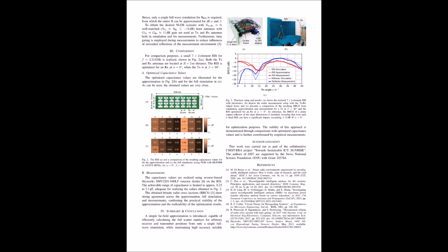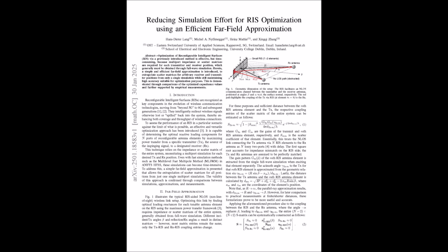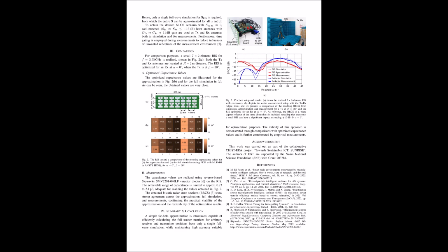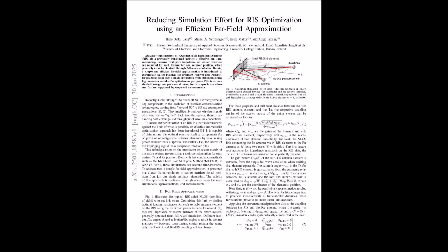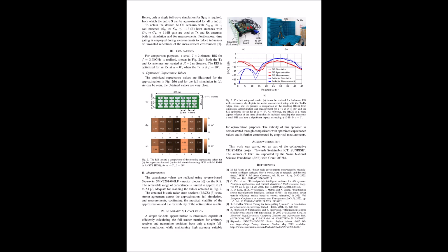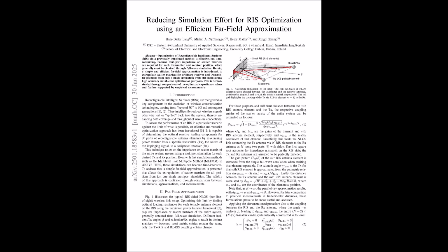And the values in this matrix, they can be complex numbers. Complex numbers, not just simple magnitude. Right, complex numbers, because we need to capture both the magnitude and the phase of the coupling. The magnitude of the complex number represents the strength of the coupling, and the angle of the complex number represents the phase shift introduced by the interaction between those two elements. Ah, the phase shift comes back into play. So we're not just looking at how strongly the elements are coupled, but also how their signals align in time. Precisely. That phase information is crucial.